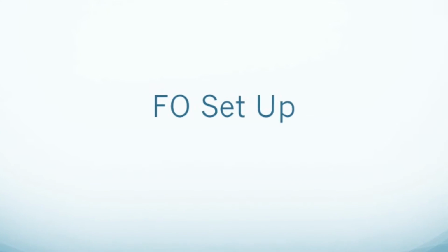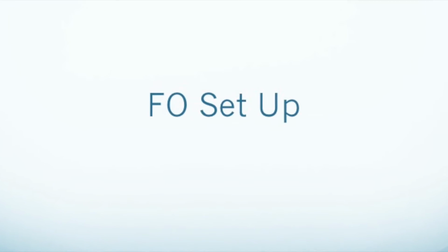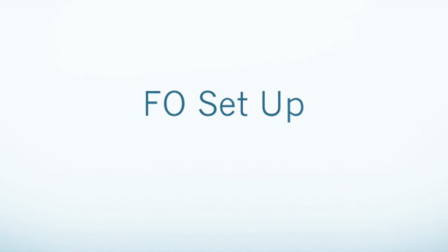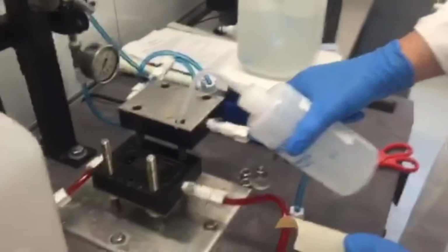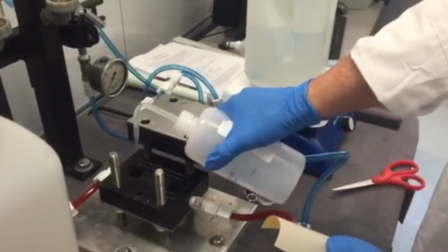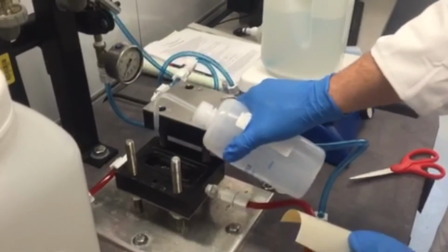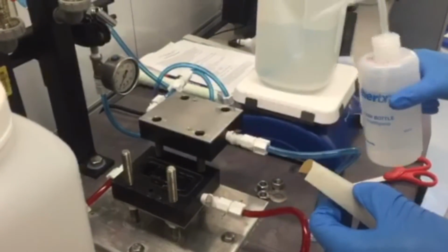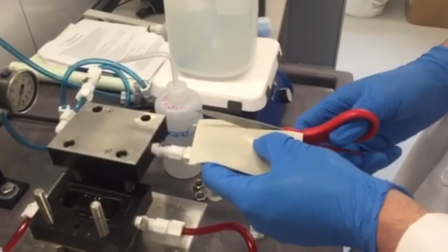Load the HTI TFC membrane into the cell with the active side facing down. It may be necessary to cut the membrane in order for it to not touch the outer rings of the cell. Place top half of the cell on top of the membrane and place the washers and nuts on the designated bolts. Tighten with the wrench in an X pattern.